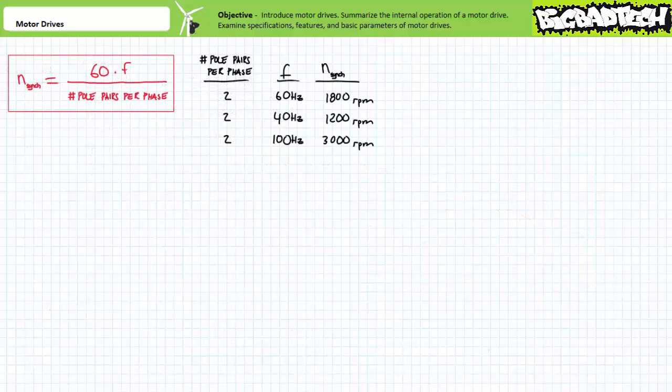The same motor will experience a proportionally increased synchronous speed of 3000 RPM. Assuming a 100 Hz maximum output, this motor is now theoretically operable inside a 0 to 3000 RPM range with no quantum jumps between fixed speed levels. But wait, that's not all.